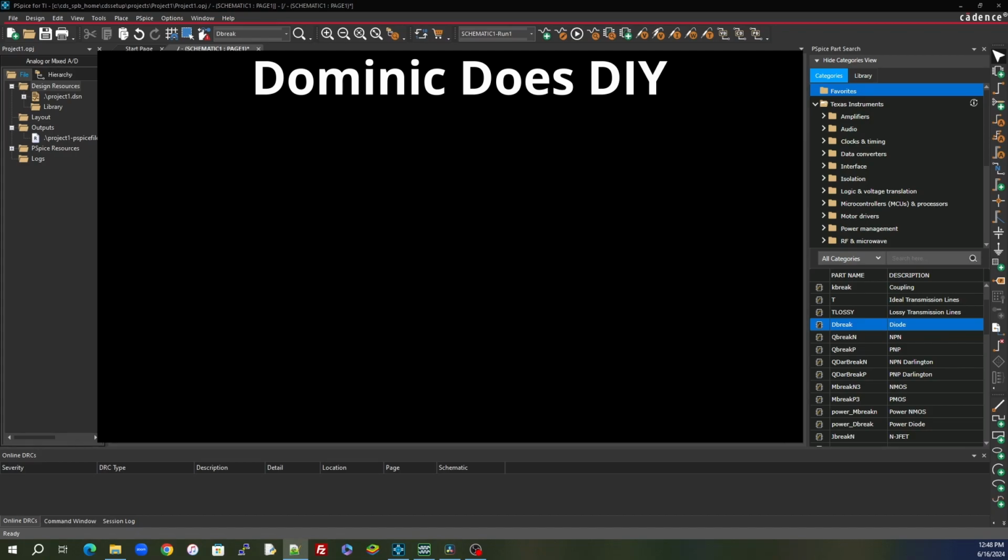So the problem with the battery is that it has internal resistance. That internal resistance, while small, doesn't do much when you're trying to run an LED or a microcontroller, where my max output is going to be 150 milliamps. The internal resistance on a battery is pretty insignificant. You don't really have to worry about it, even up to maybe 1 amp, 2 amps. You're probably not too concerned about the internal impedance. It really is when we get up to 10, 20 amps, something like that, where this internal impedance starts causing an effect on our circuit that we have to be aware of.